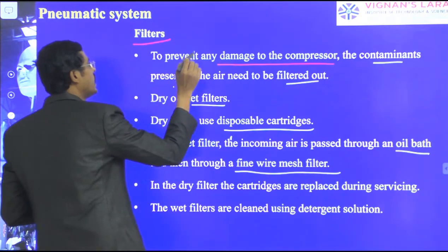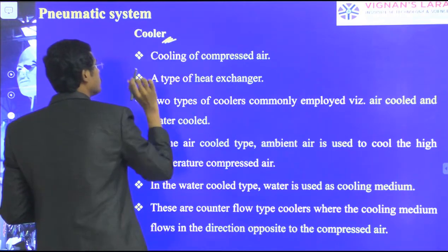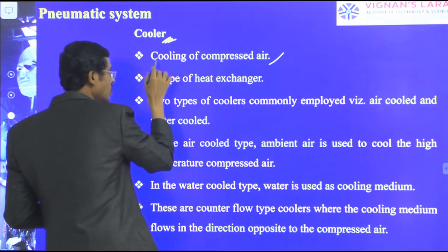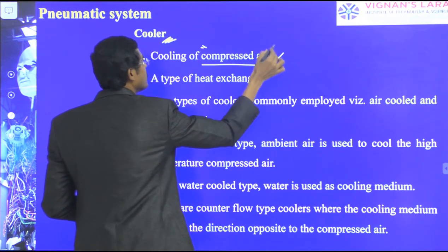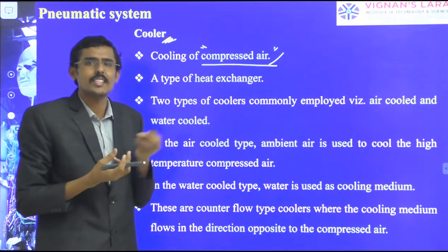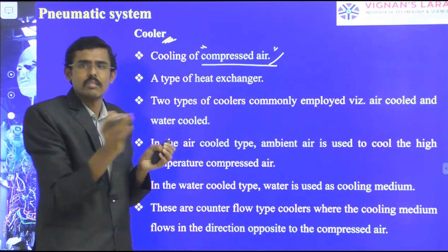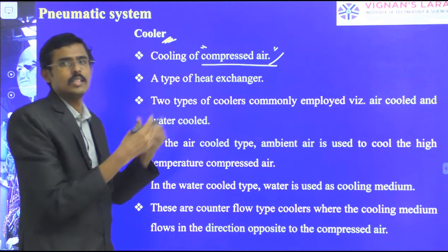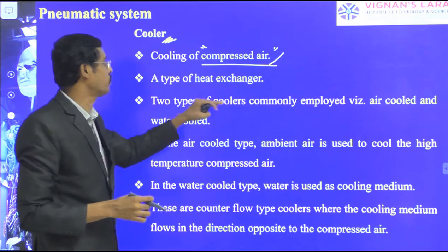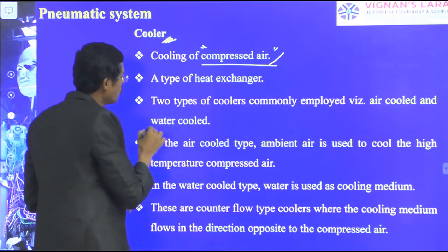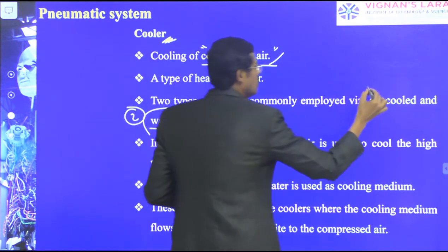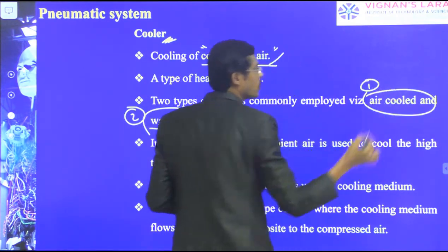To prevent any damage, we use coolers, which cool the compressed air. It is a type of heat exchanger, because it removes the heat separately from the air in compressed form. Two types of coolers commonly employed are air cooled and water cooled. So one is the water cooled and one is the air cooled mechanism.